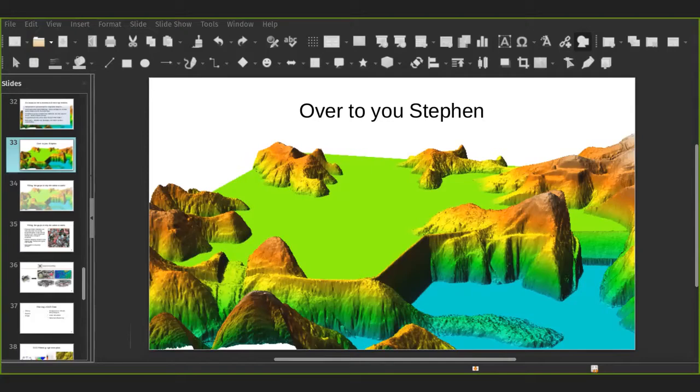For example, flying elevation models in low-cost environments where LiDAR might not be sustainable, or filling in time series between LiDAR flights with photogrammetric data. I won't talk much about this in the presentation, but the data flown for the Zanzibar Mapping Initiative was optimized for orthophoto creation. As such, this is a really challenging data set for getting elevation models out of. I co-founded OpenDroneMap a few years back. It's become a pretty useful tool for projects like this. I'm not going to talk about that today, but that's what feeds the data in.